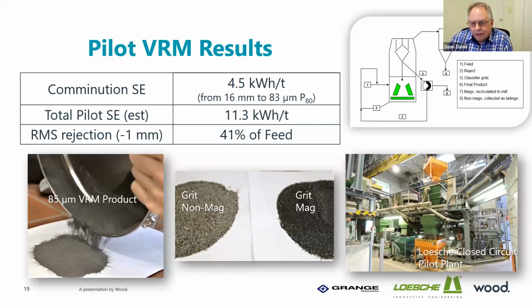Fortunately, a few months later, another test was done. And immediately it was done, we were able to grab some of this material, put it under nitrogen, get it to the laboratory, do its first mag separation, and then do a lab float test immediately. Very similar to what would happen in an operation. It would come out of the VRM and be straight into mag separation, then flotation. The response was the best we'd seen for any test ever on this material. And it was very clean float, very fast float. And we got down to levels of sulfur that were 0.02 against a target of 0.05.